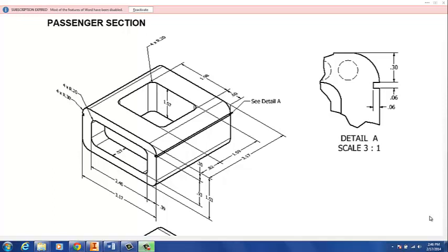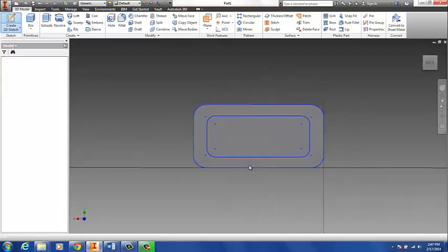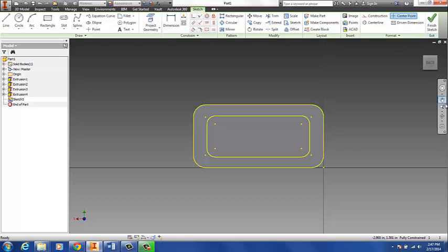We have a couple more steps. The next thing we'll do is put this notch through on both sides. We can get a detailed drawing here. We can see it's really just a square 0.06 by 0.06 that is 0.3 down. So put another sketch here, and we'll zoom in.